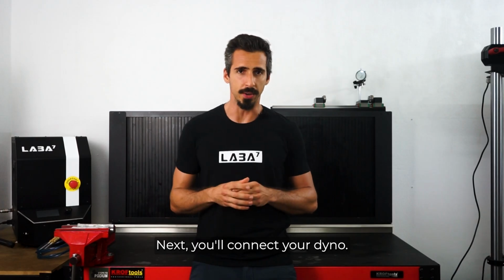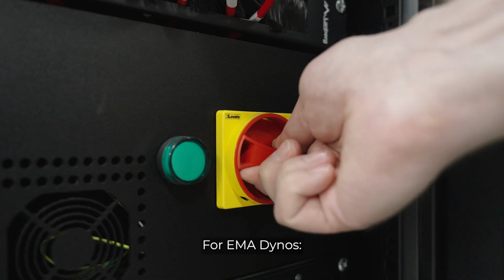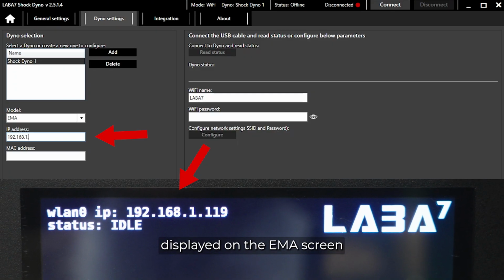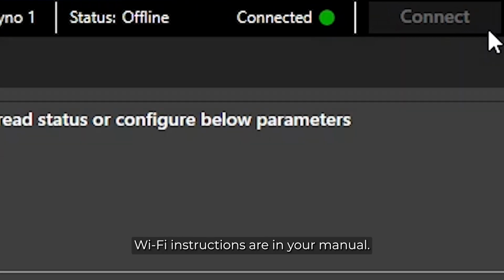Next, you'll connect your Dyno. This process depends on whether you have an EMA Dyno or a Scotch-Yoke Dyno. For EMA Dynos, turn on the Dyno. If using Ethernet, connect the LAN cable. Enter the IP address displayed on your EMA screen and wait for the green online indicator. Wi-Fi instructions are in your manual.